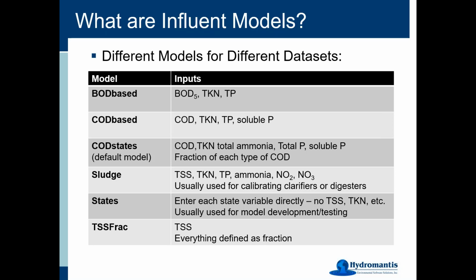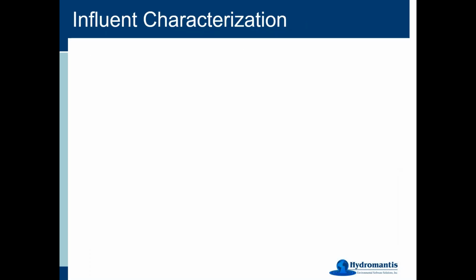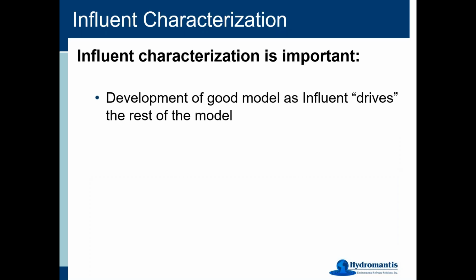Okay, so let's move on. Oh, I would mention, by the way, highlighting that the COD states model is the one that I personally prefer, and I know that most of the people who use GPSX like this. That's why we've made it our default. So I do recommend using COD states most of the time if you can. I know you don't always have COD data. Sometimes you're stuck with BOD and you've got to go from there.